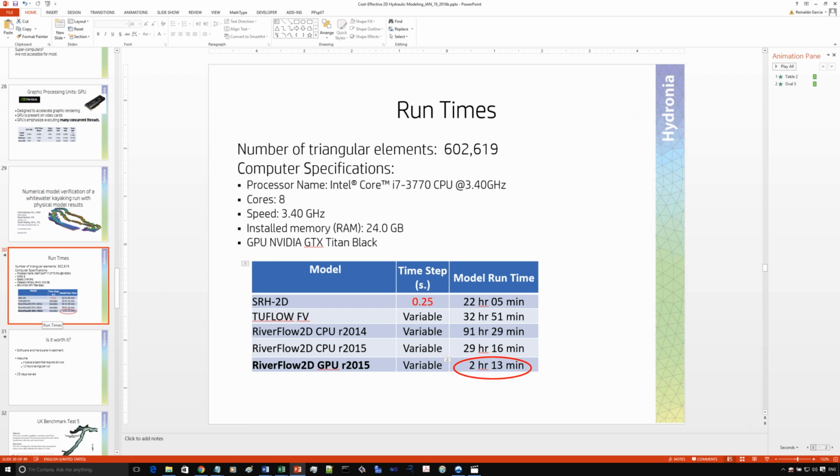Is your software able to set a variable time step to improve stability of the model? Actually, in RiverFlow2D, you don't need to improve stability. The model will always be stable. I haven't found a single case where the model becomes unstable in RiverFlow2D, and I can tell you I've seen quite a lot of simulations coming from many users worldwide. What the model does is automatically adjust the time step to ensure stability, consistency and convergence always. You don't need to pay attention to that, and that's one of the reasons the model is so efficient in doing actual project work.